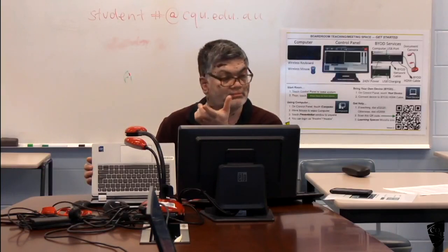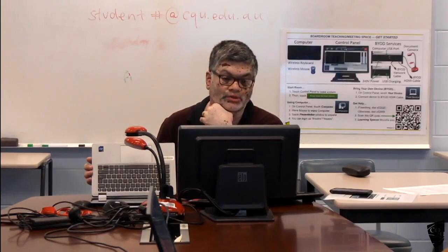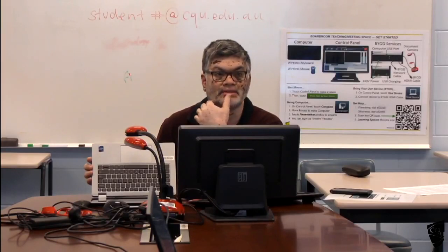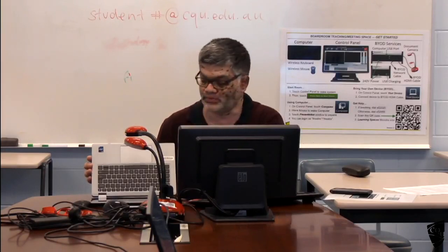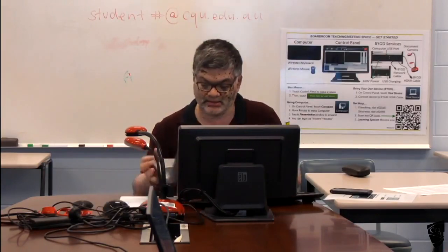Ft is the design load. Lx squared, you know, the shorter span. The beta x, beta y, you can get from the table 6.10.3.2.